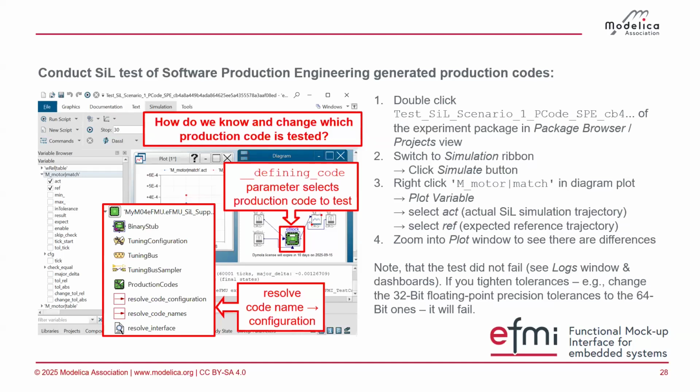And second, if you use the eFMI export, also Dymola, if we generate names that are unique based on the configuration, you get a path length of 500 and higher, and then you die. So in Windows this is the way to avoid the max path length issues.